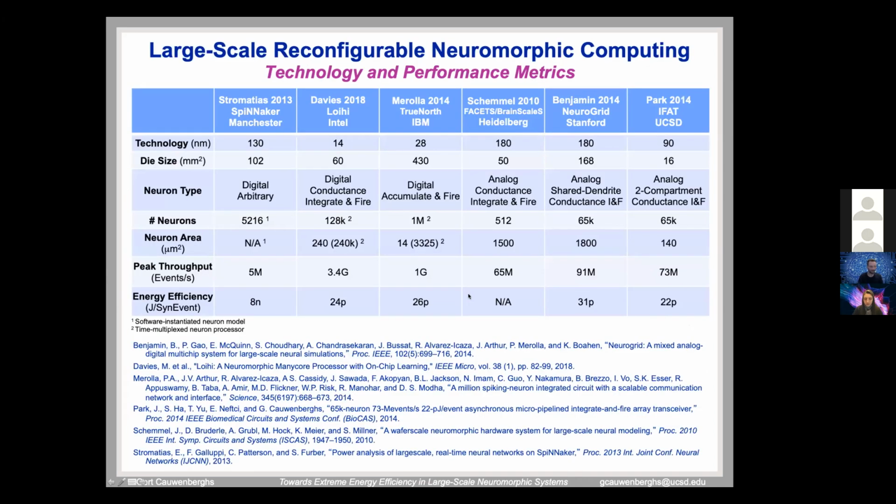So here is a summary of some systems out there and their limits. And so this tutorial being about efficiency. It's not a complete list, but this is mostly systems that are reconfigurable with spikes, and they have a large number of neurons, right? And so they're all reconfigurable. So any neuron in principle can connect to any other neuron, and that's all defined in this event-based representation, right? And so you have neurons ranging from a few hundred to a million here, right?